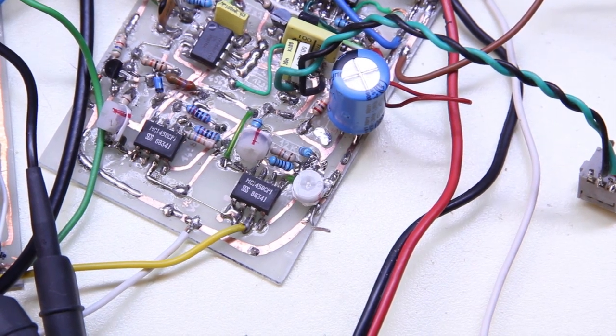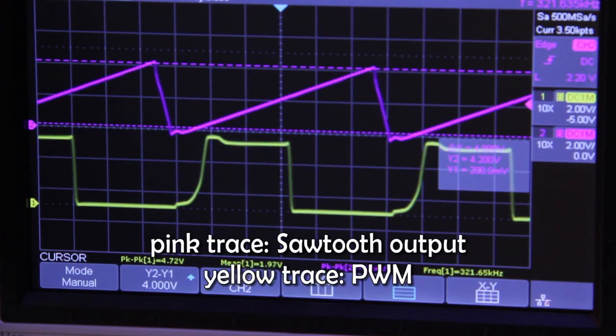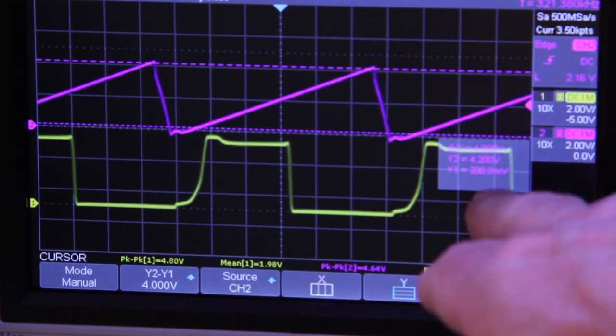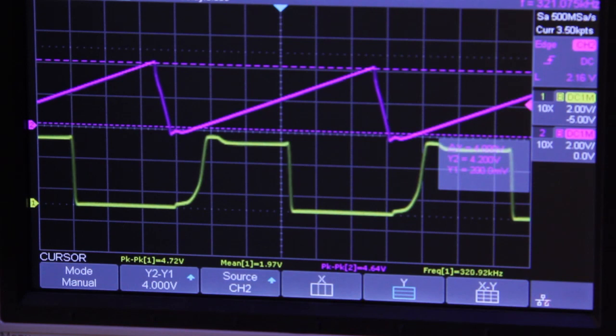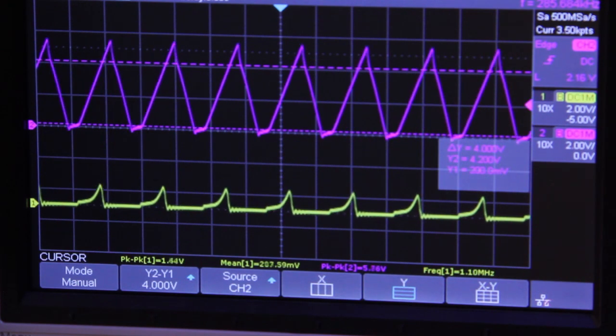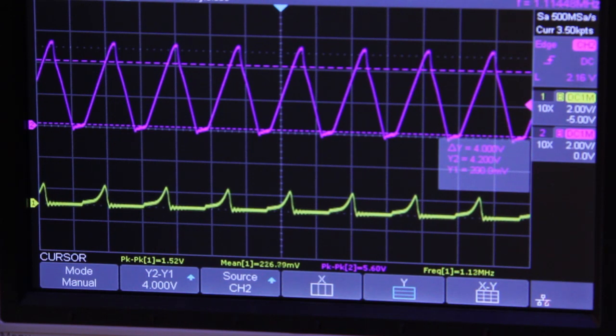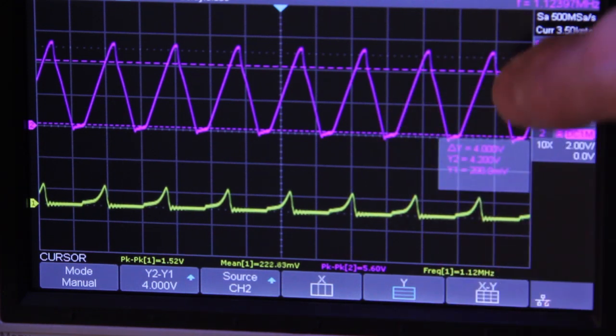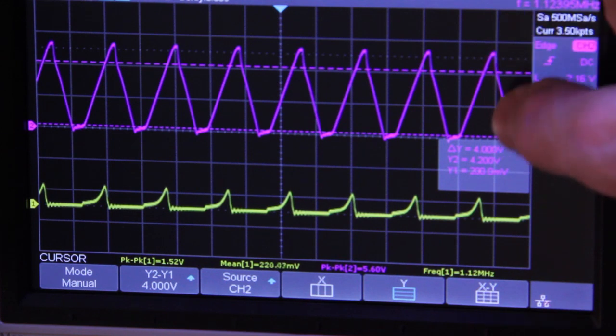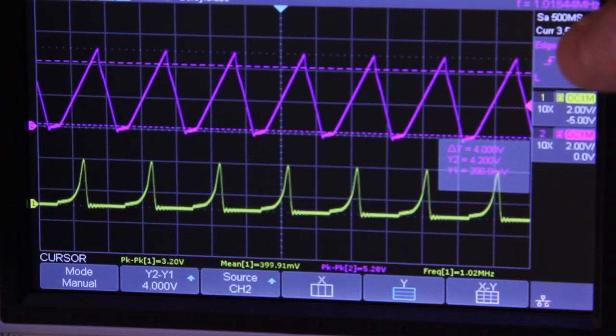And so let's have a look at the oscilloscope, see some waveforms. Okay, the output of the PWM generator, but this is a topic that we will see in another video. It is just for reference here. And let's change the frequency. We can go up to the maximum. Maximum is 1.1 megahertz, but as you can see, the signal is quite distorted at 1 megahertz.